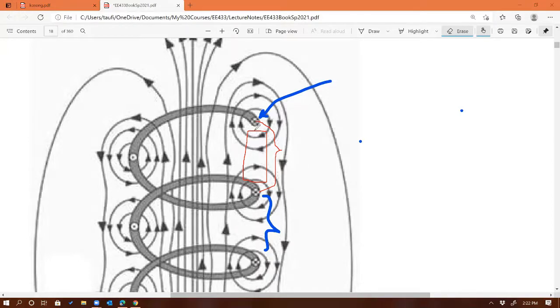If they couple to each other, then what? Then you have leakage inductance, basically. So you have some flux coupling each other that is not supposed to be coupling. That would create more parasitics, parasitic inductance for this coil. So this is a simple and effective way of canceling flux between windings, between turns right there. The reason is that you don't have any flux coupling between each winding. If it does, then you're going to have some parasitic inductance, and that's not desirable, okay? Is that clear?